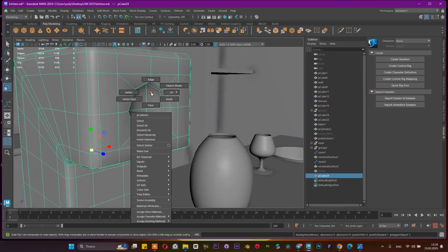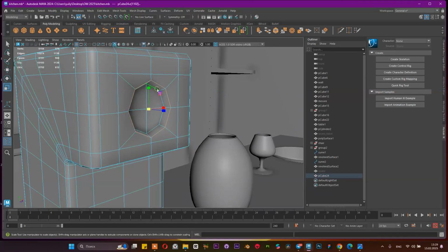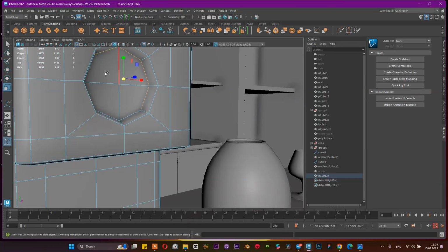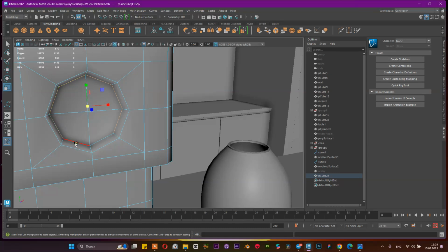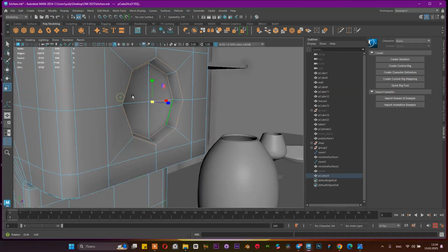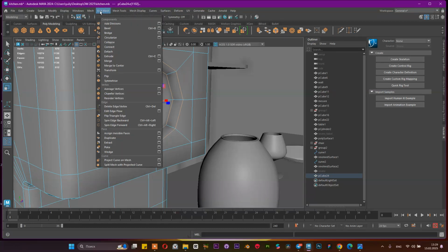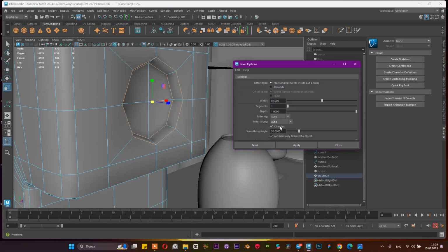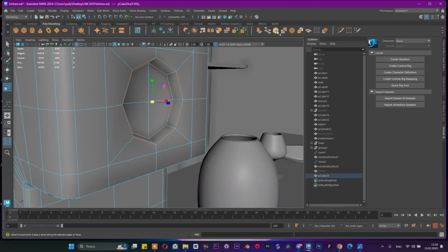And if I add some bevels on these corners, for example, I can select inside edges and outside edges, and in the bevels we can open bevel settings. Inside of the bevel settings we have chamfers, and maybe let's make bevel.